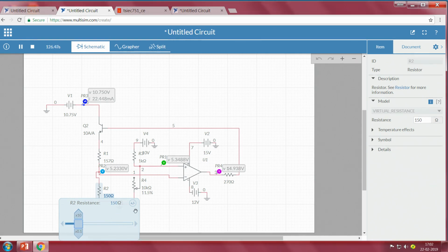So this was the brief introduction about how you can simulate an anemometer, the 4 arms of the bridge driving through which are fed to the op-amp and then to your transistor. Assuming this is an ideal condition, we have used a compensatory circuit at 30 degrees Celsius and the relative resistances are chosen accordingly.